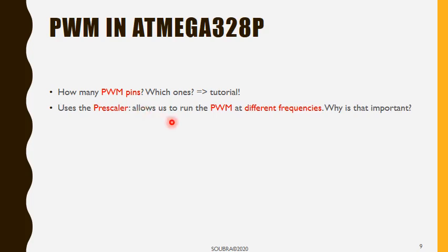The idea is how to deal with the frequencies, and we've seen from the watchdog timer that we use a particular digital component when it comes to getting different frequencies from one general oscillator or clock. Yes, it is a prescaler, also known as a frequency divider.